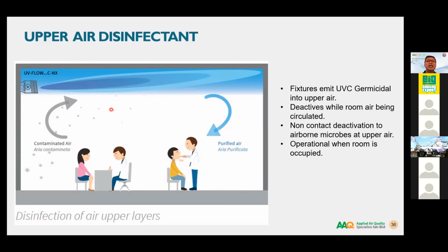So our normal Asian height is around 5 feet plus, 6 feet. Very seldom can you get over 6 feet. So the UV ray is angled upwards, above the lower grill. So it's channeled upwards to concentrate and focus to deactivate the microbes in the upper air part. This way you can enjoy and operate the upper airstream 24 hours even if the room is occupied.